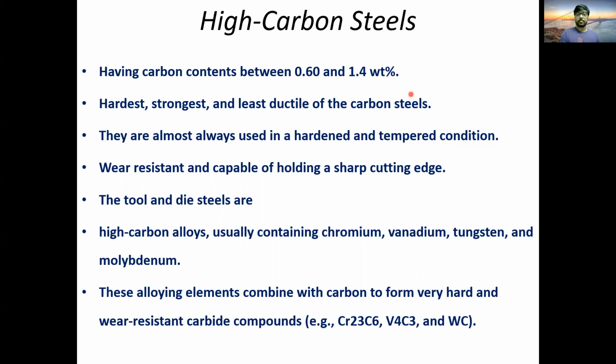Again, the same logic comes as we increase the amount of carbon: the ductility decreases, and the hardness and strength of a material increases. Okay. So as this has a better amount of carbon, it can be easily heat treated. So we can apply heat treatment and get the desired properties.